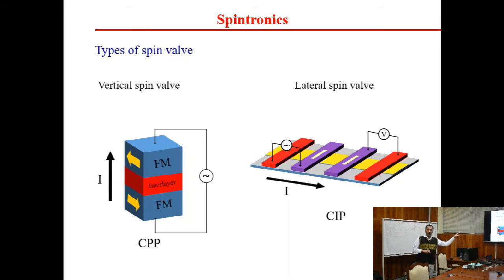If you see some kind of effect in that region, what will happen? You will see the diffusion of the polarized electron, which can create a potential difference between these two electrodes. This change in potential difference at these two points should be the spin current, because the path of the charge current is between the other two electrodes. You are measuring the current in the other region, which is due to the diffusion or spin polarization of the electron at the other end of the electrode. If time is short, I can discuss in detail later if you want.